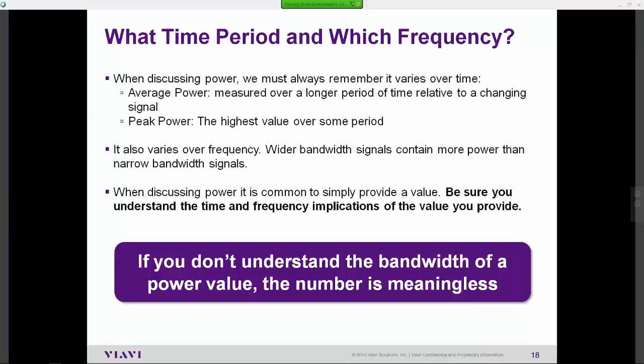But also recognize this, within a spectrum analyzer, before that first line trace gets shown, there's actually a variety of samples that are taking place even before that line trace gets presented. So recognize that in your setup of your instrument for your trace display, you will find that there are settings that can default to RMS values, which says, okay, we're going to do the root mean square on all these values, so we're just going to show you a very clear presentation of spectrum. But many of the veteran people out there that I've met that have done interference hunting say their single greatest asset is to actually change that setting to peak power.